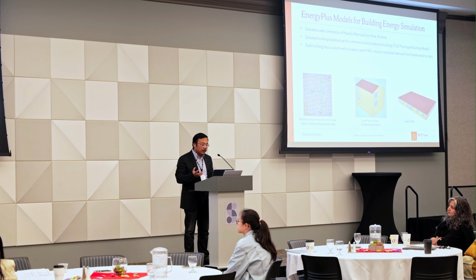And then we use EnergyPlus as a modeling platform. We actually simulate a real community in the Phoenix area in Arizona, and this is an actual community. We replace each building with DOE prototype residential buildings and simulate every building in this community. Each building has customized occupancy and HVAC set-point schedules derived from the human data.